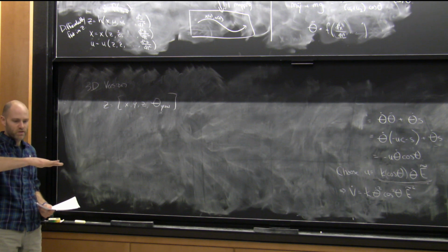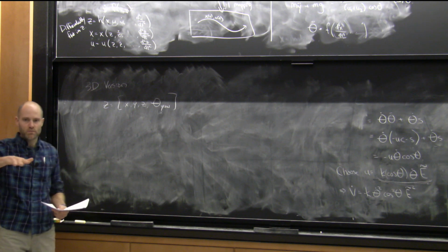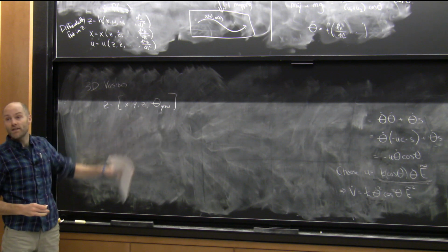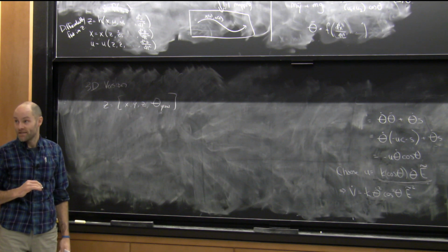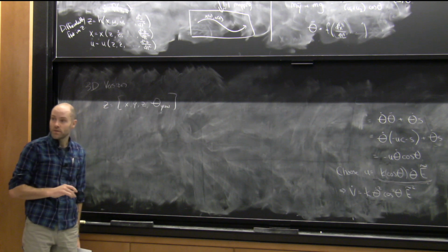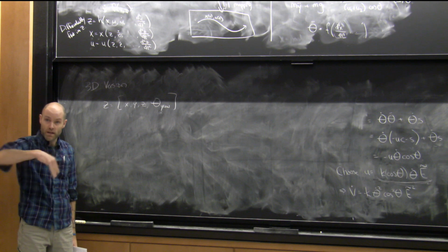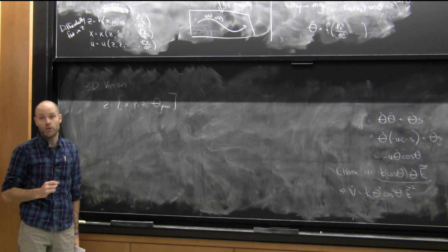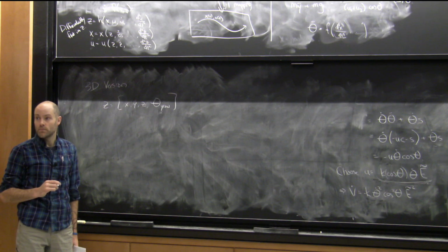That's roll, that matters a lot. The yaw, you think maybe shouldn't matter so much, but these are the outputs that people know to be flat. If you specify these for all of time, then it implies what your pitch and roll had to be doing over time, and what your propellers had to be doing over time. Okay?